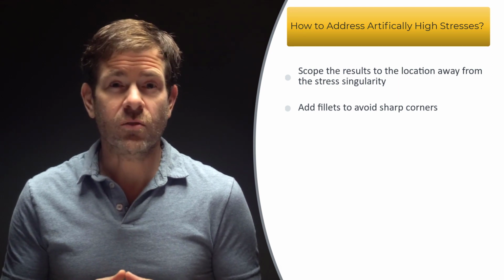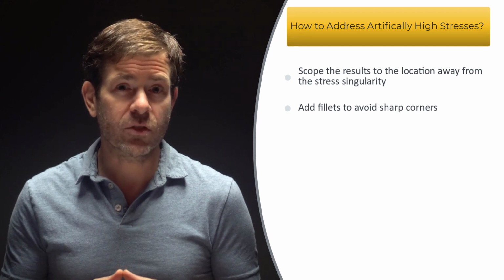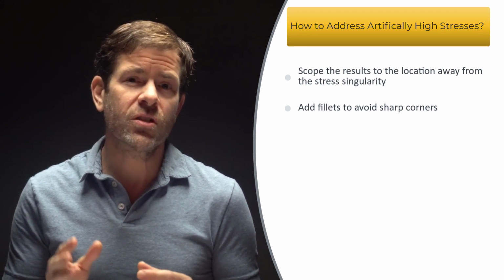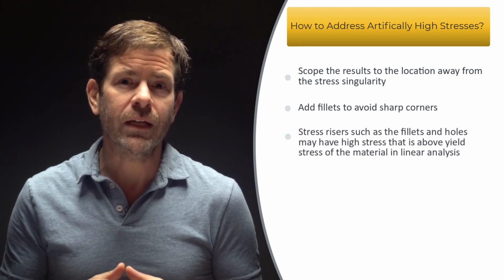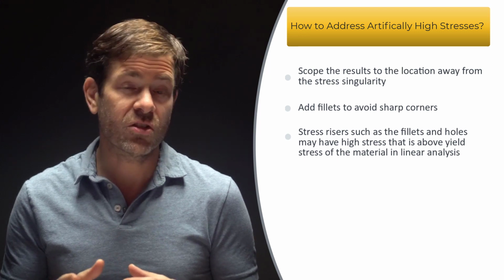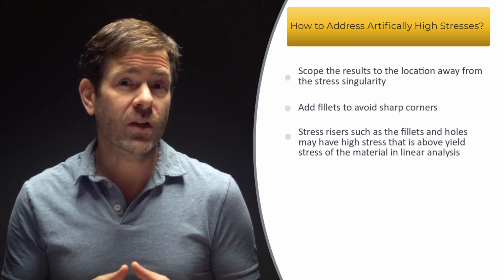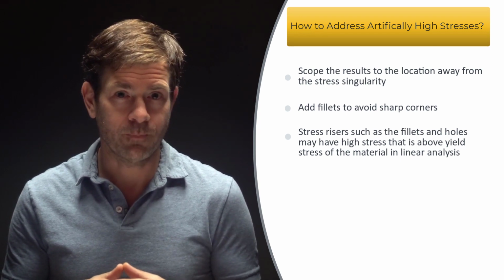In this case, the stress will no longer be singular. You may need to have small elements to resolve the curvature of the small fillets, but you'll find that the stress converges with mesh refinement. It's also worth noting that stress risers, such as those at small features like fillets or holes, may have high stresses that in a linear analysis will exceed the yield stress of the material.